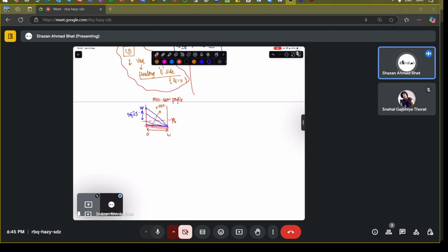So what is going to happen? This particular curve is almost having slope approximately equivalent to zero. So as a result, there will be a low current flowing. Low current means low IE will be flowing, and this indicates that there will be low IC flowing in the overall system. So what does that mean? If you have a low IC flowing inside the system, you will have higher breakdown voltage, because the collector current flowing is very small. If you have a huge collector current flowing inside the system, then it will relate to earlier breakdown.